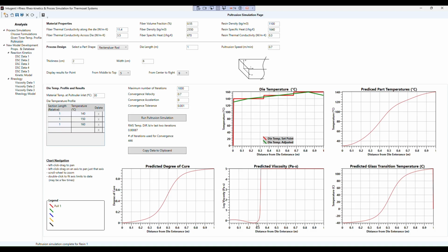The minimum viscosity of resin before it gels is a very important factor in determining whether resin will penetrate through the tight spaces between filaments. As resin gels, its viscosity increases drastically, and it shrinks. Low viscosity profile and proper gelation position are very important in determining the pull force and surface quality. It is usually preferred that material gels within 30 to 40% of die length.